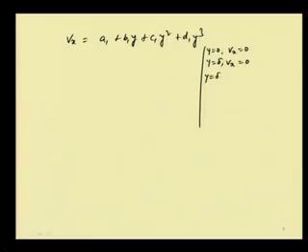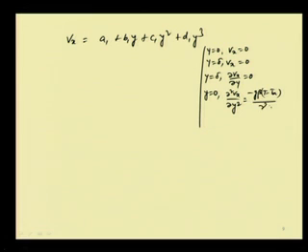Again at y equal to delta, we know that del Vx by del y is equal to 0, and at y equal to 0, del square Vx by del y square will be equal to minus g beta (T minus T infinity) by nu. How do we get this expression? We can pretty easily understand, it is coming from the equation of motion.